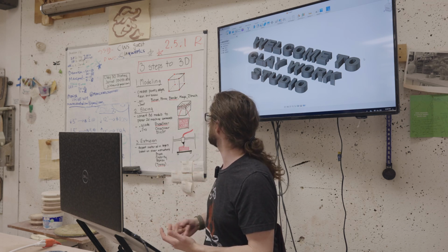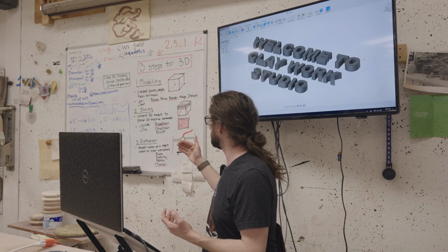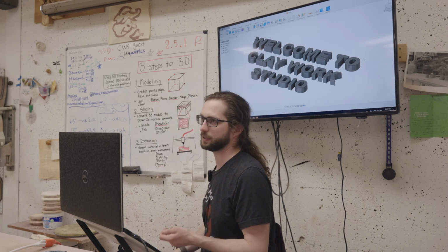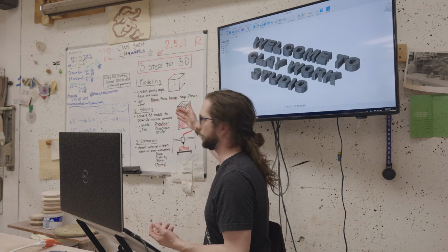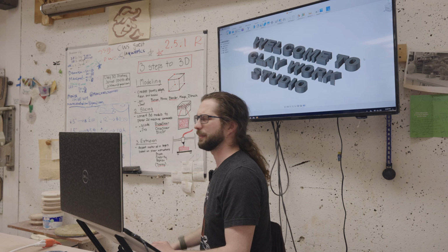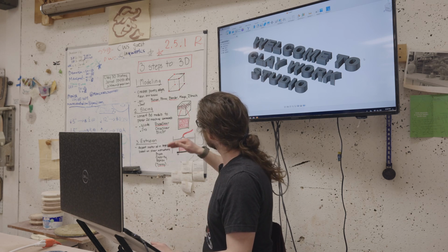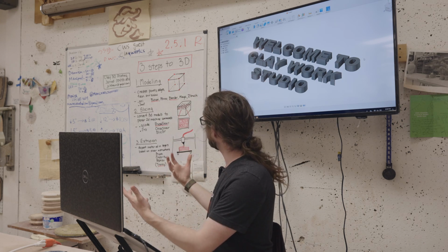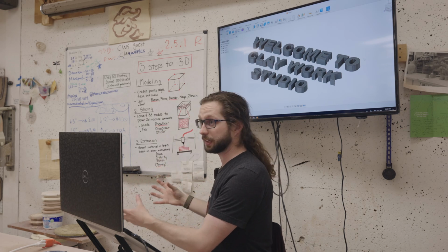I don't know if Blender uses 3MF yet, but Fusion certainly does, and going from step 1 to step 2 with 3MF is a little bit less complicated, so we'll tend to prefer that, but I'll talk about them interchangeably. So if you hear me say, we'll look for the STL, I might actually mean 3MF, so don't get confused on that. So after step 1, what we have is a bunch of points and faces and edges in space that are represented by a file.